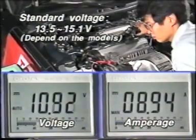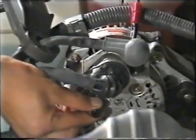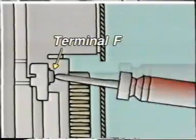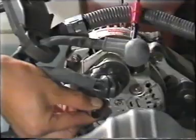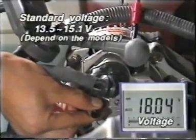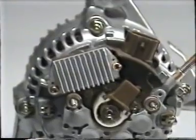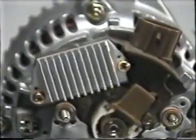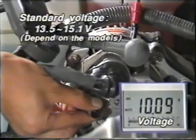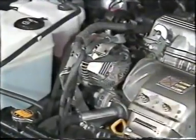If the generated voltage is lower than normal in this test, recheck it after grounding terminal F to apply the battery voltage directly to the rotor coil. If the generated voltage goes above the standard value as a result, there could be a fault in the regulator. If the voltage is still too low, on the other hand, a fault in the alternator is likely. In that case, the alternator must be checked.